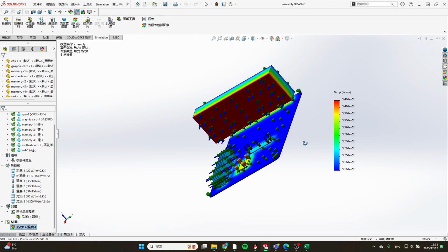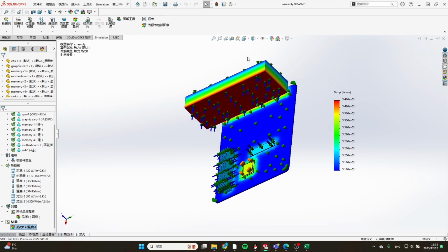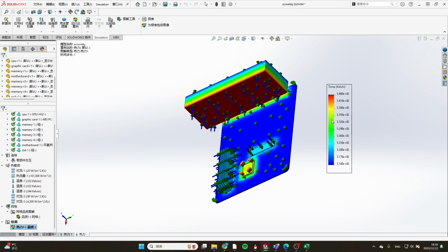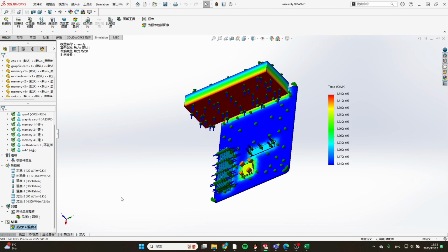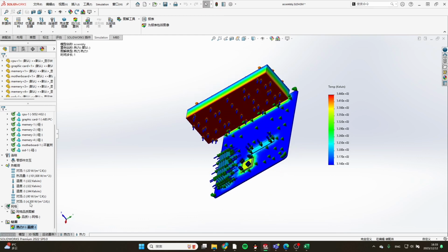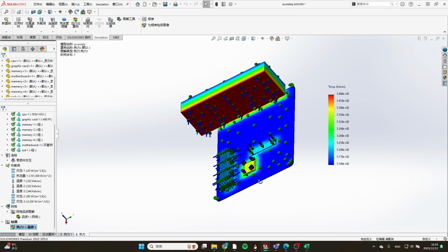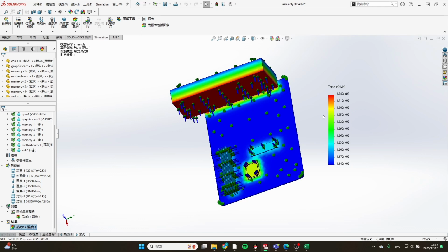So this is the SolidWorks model we generated. The result has already been passed out here. There's a bar column targeting the temperature. What we did for testing is to assume some values at first. It might be kind of hard to read, but you can just look at the image. The temperature tested, and the convection heat transfer coefficient for the GPU and motherboard. I'm assuming this value, and I will show it's not necessary to assume an accurate value. And this one is the output value. We change this value until the surface temperature of the CPU reaches the target.